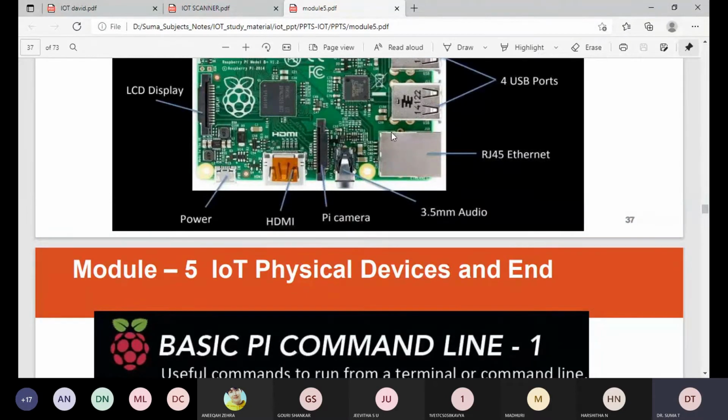The recommended and easiest way to power the Raspberry Pi is via the micro USB port on the side of the unit. The recommended input voltage is 5 volts and the recommended input current is 2 amperes. The Raspberry Pi can function on a lower current power supply, for example 5 volts at 1 ampere. The minimum will be 5 volts, 1 ampere.